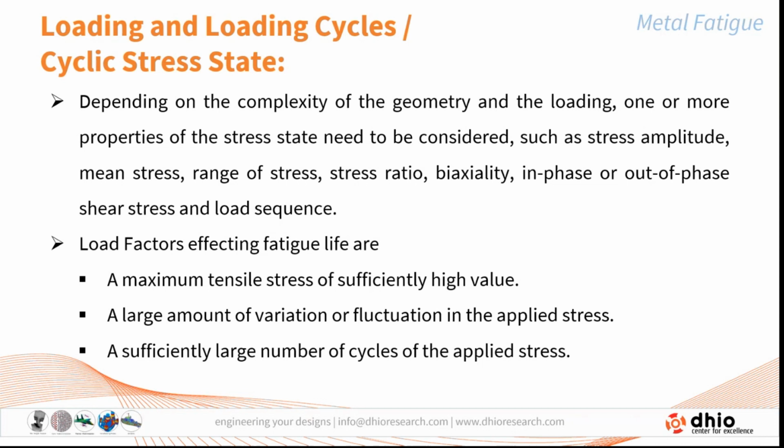Now, depending upon the complexity of the geometry and the loading, one or more properties of the stress state need to be considered, such as the stress amplitude, the mean stress, the range of stress, the stress ratio, the way in which the stresses are acting, whether uniaxial, biaxial or multi-axial, and if multi-axial, whether in phase or out of phase, or whether they cause some shear stress, and the sequence of loading. All these things are going to affect the fatigue life of the component.